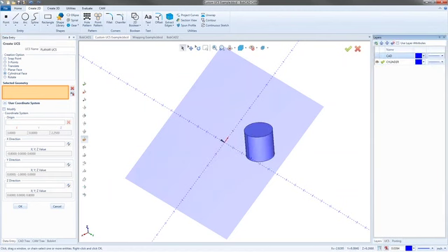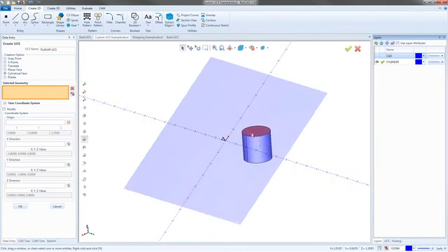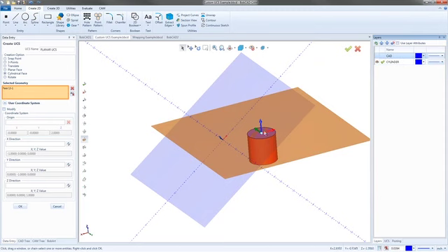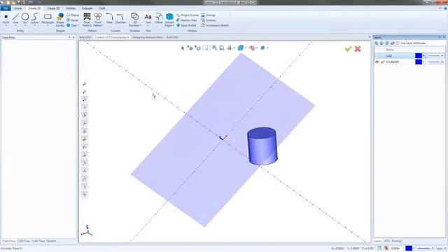A cylindrical face allows you to choose a cylinder, and then it's going to normalize off that cylinder to the top of the part. So what we'll see is we pick the cylinder, it figures out the X, the Y, as well as the Z. If you wanted to do the top and just let it figure it out, you can do that as a planar face, but a cylindrical face is to pick a rounded, a cylindrical piece of geometry. And then the last one is the rotate command.